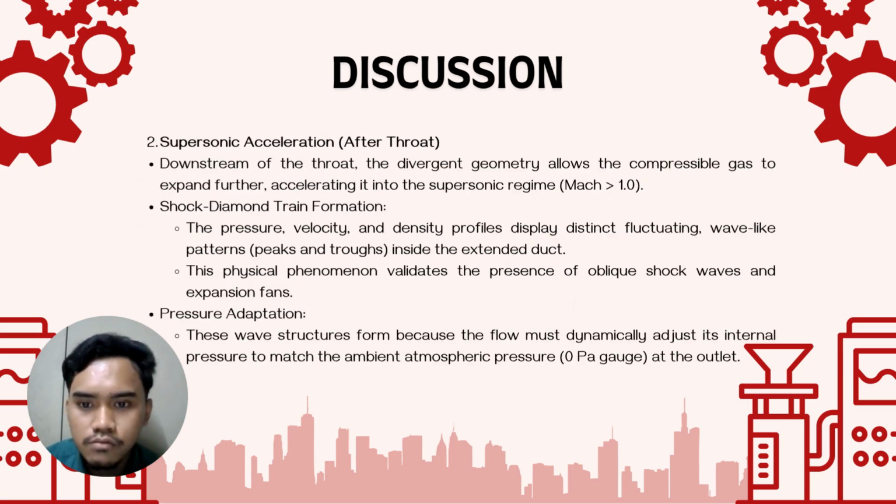Now we are going to talk about the supersonic acceleration, which is after the throat. Downstream of the throat, the divergent geometry allowed the compressible gas to expand further, accelerating it into the supersonic regime, which is more than 1 Mach. So, shock diamond train formation, as we can see in the contour of the result.